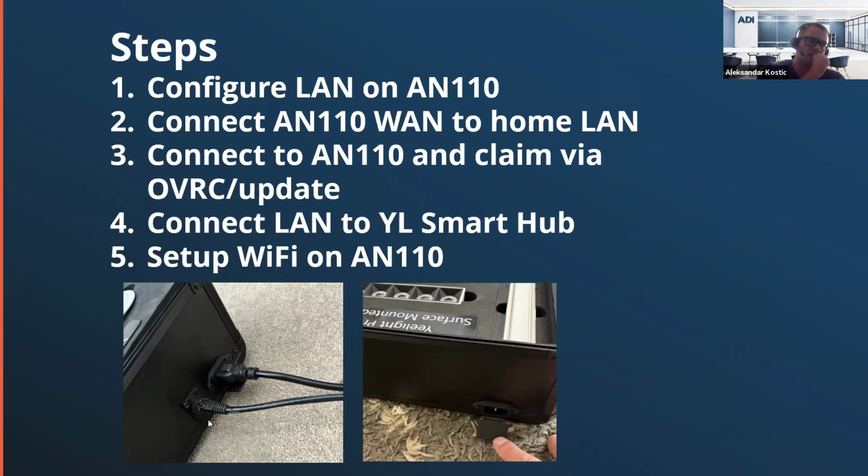What I mentioned regarding the demo case, those are like two connectors which are available outside. One is for the power supply, and the other is for the network, providing the internet connectivity to the router. And just have in mind that this connector where the network cable is plugged in is not connected from the inside. So from the inside of the case, you need to put like a small patch network cable going from this connector to the router itself. Speaking about power supply, you do not need to do anything there. Everything regarding power supply is already wired inside. So you just need to plug in power supply, nothing else.